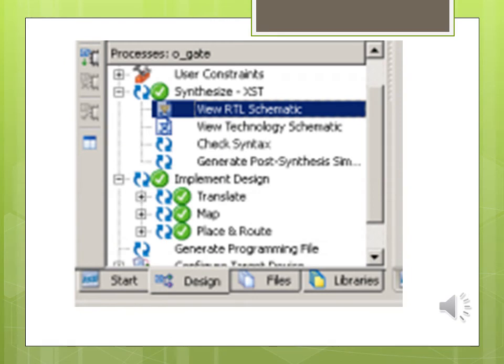After the logic circuit is fully designed and merged into one circuit, it is translated into a netlist of basic logic gates. Then it is mapped to a netlist of Xilinx logic cells. Then placement and routing is done.